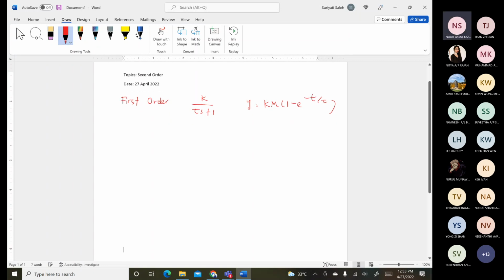The main reason we develop the first order is because we have the ready-made inverse Laplace. So this inverse Laplace normally gives the response. The purpose of having the inverse Laplace is to solve the problem, to obtain the values which we will plot for obtaining the desired response. Normally, we will employ the step input. So this is what we call the step input, the change based on the magnitude M.